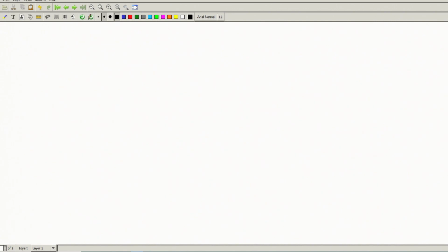The slot and the ground plane can be viewed as a transmission line, and the field in the slot will be essentially a harmonic function of kz. So, we were given a slot of length L and width W, and this is Z.